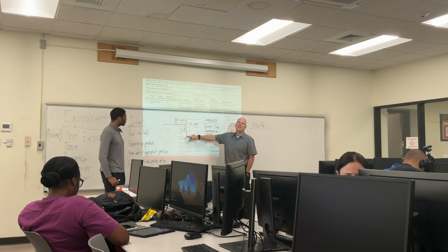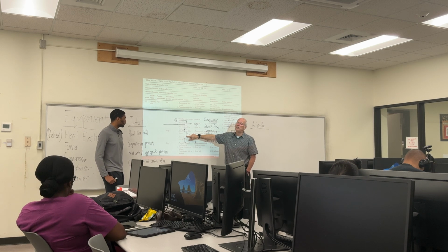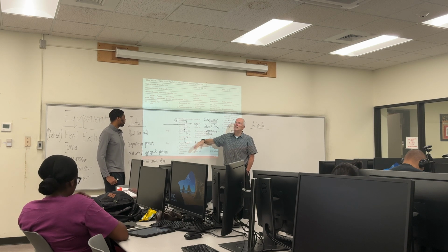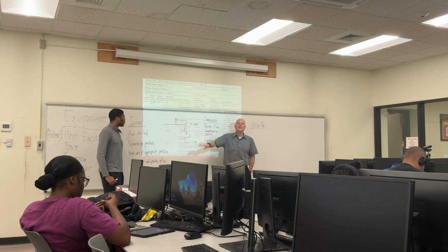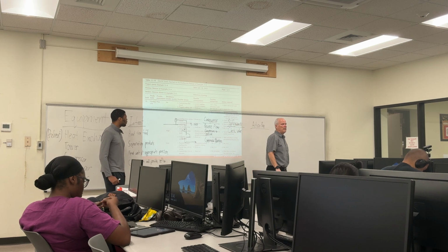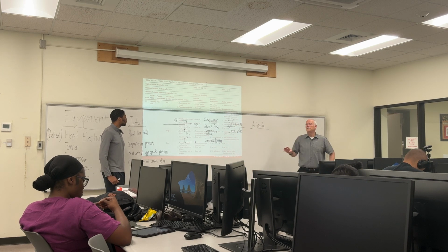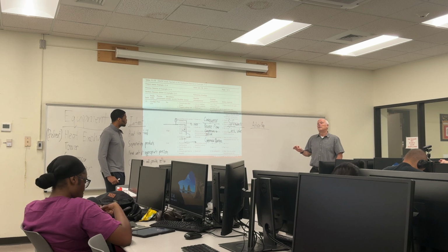You would have a speed controller that's separate from that, that also makes sure that the compressor doesn't run at its critical RPMs, because that would destroy them. And that's generally a PLC of some sort. And it also has shutdown systems. If you try to run there, it'll automatically shut the compressor down and shut all the valves around it.